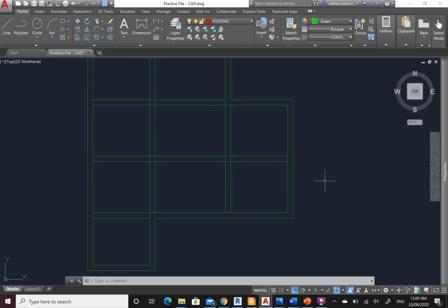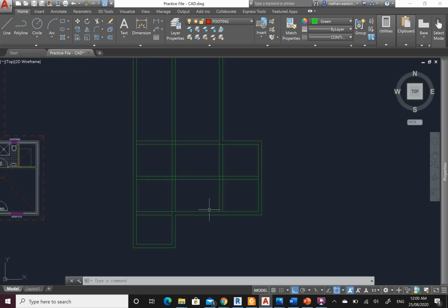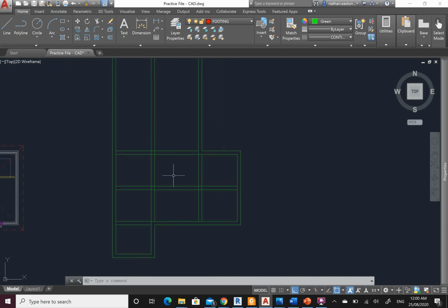But in the X direction, this footing here isn't the edge footing. So part of the standards lets us, if this footing here, which is the first one, is less than 4 meters, make up 25% spacing in between. So what that means basically is this one's alright. We can get away with it. So we will leave this one here. This one here, same thing, it's okay.